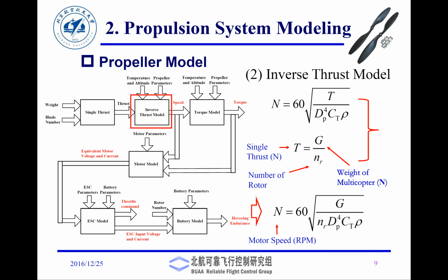So what you do is, first you find out the amount of payload, and then you find out the approximate self-weight, and then you find out a particular prop, and then you find out the speed at which that prop has to rotate so that the quadcopter or octocopter has enough thrust to lift itself and the payload.